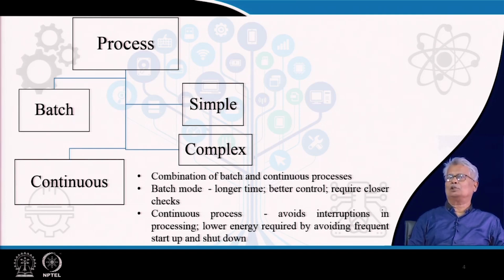So, one thing is true, that in case of any batch process there will be startups and shutdowns. And you also have to remember that in any batch operation, the entire feed material of the batch is normally fed to the batch equipment in one shot. So, if I have a processing system for 10 ton per day, and if I decide that I will be doing it in a batch, my batch should be capable of holding all the 10 tons of material together.